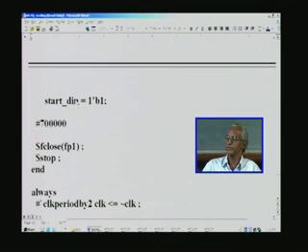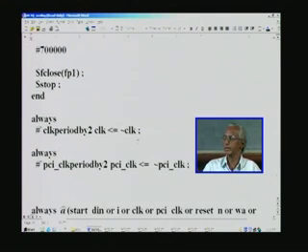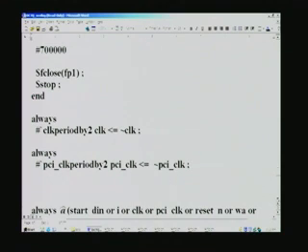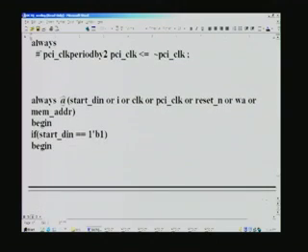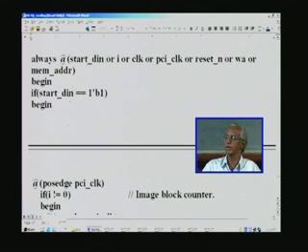Once you give the start signal, because we have already invoked the DCT design, it will start functioning. After say 700,000 nanoseconds the file will be closed and the simulation stopped, during which time you would have processed one frame of image and got it in dctq.txt as the output file. This statement inverts the clock so that the clock runs for both phases. We now have an always block to take further decisions, processing block after block. How we do that, we will see.